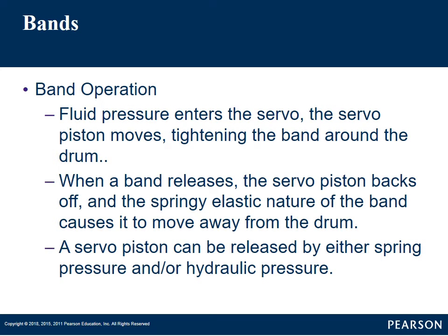But the important thing is those springs can break, and then you don't have proper application of your band, because again, that spring helps control how fast that servo piston applies. But for the most part, to release them, they have a spring, and on some systems they actually use hydraulic pressure to help push that piston back and release that band.